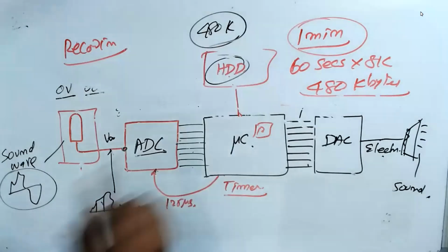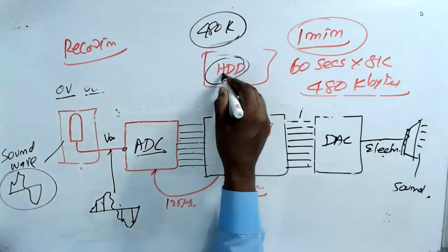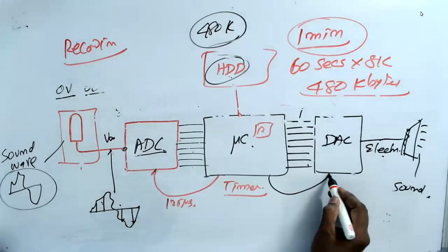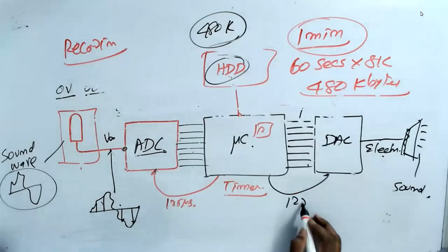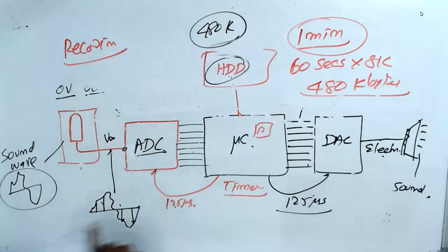Then what you will do is play it back. At that time, when you are sending it back, you have to send it at the same timing. If you don't, I sample at 125 microsecond and you should play back at 125 microsecond.